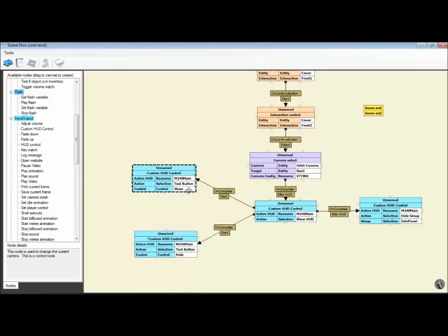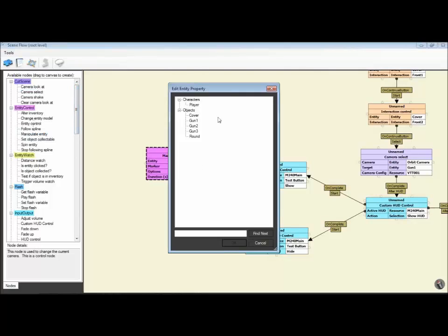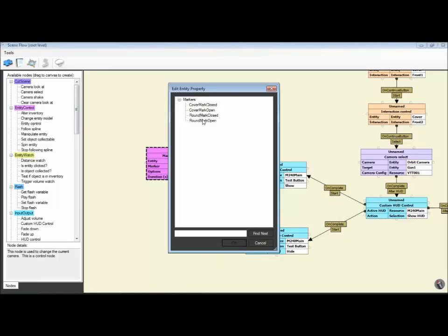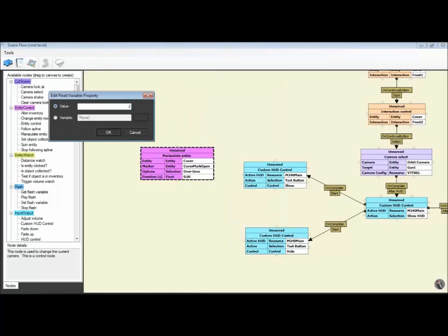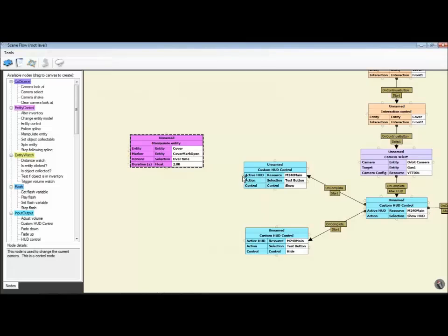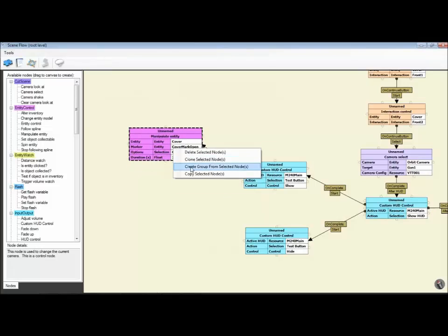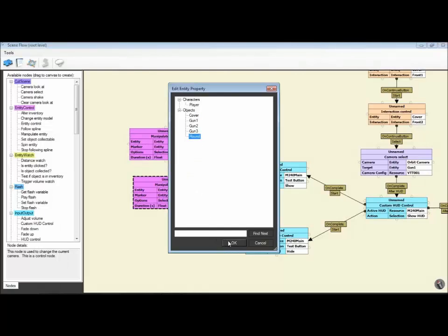When I press show, I'm going to use manipulate entity nodes to open the cover. So I want to take the cover and I want to move it to the cover open mark, and I'll set 2 seconds. Should really use a variable rather than numbers, but it doesn't look too bad, so I'll use numbers at the moment. And we'll clone that, and we also want to move the round to the round open mark.